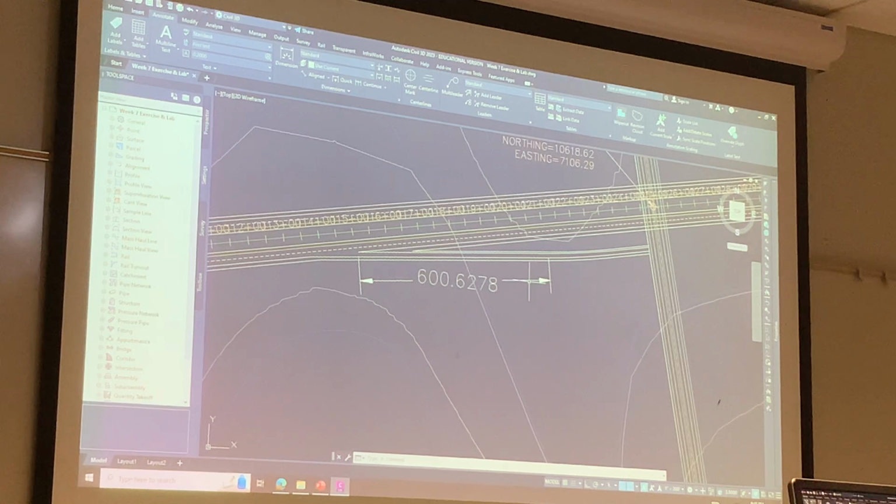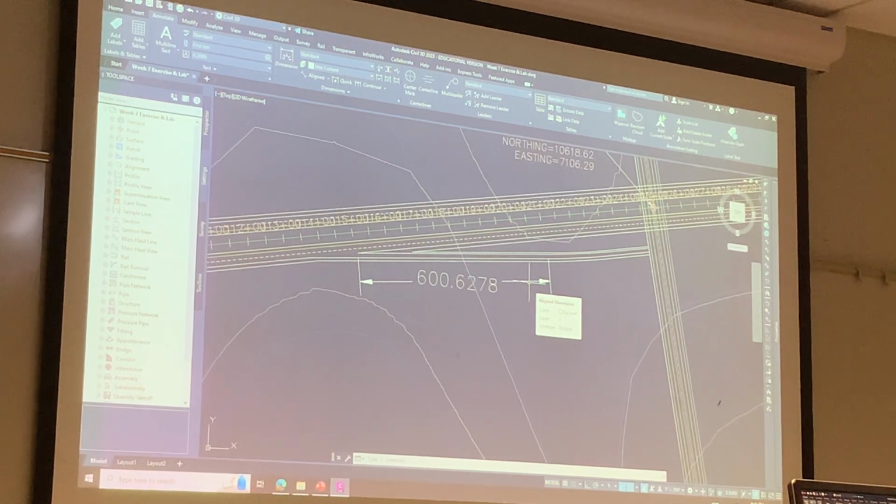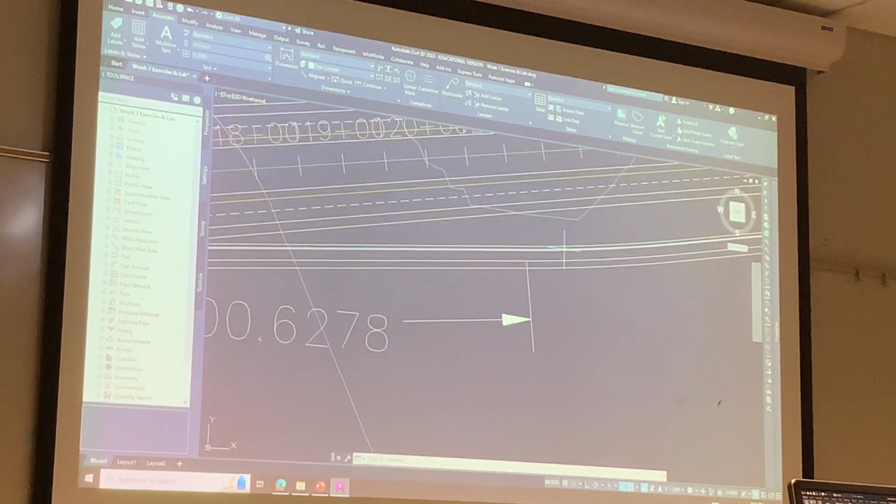So if it's 700 over 950, that's 74% of the change of 40 miles an hour. So it's a change of speed of 30 miles an hour, which is 3/4 of 40. I'm reducing by 30, so I'm going from 65 to 35. So my design speed is going to be 35 miles an hour on this curve on this off ramp.